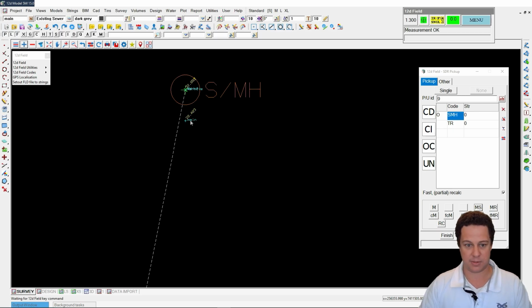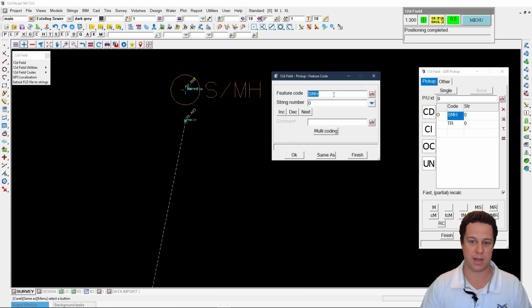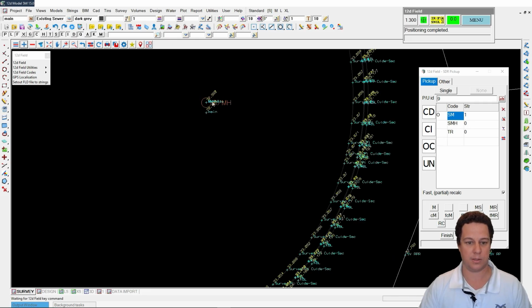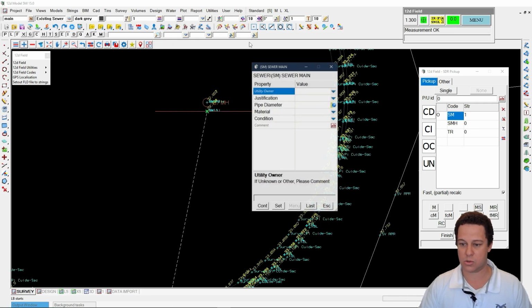Let's go ahead and pick up the sewer main. So I'm going to come to this guy here, and we need to change the code. So we'll come back to our CD button. Now I know that sewer main is SM, not SMH, so all I need to do is backspace that, give it a string number. Let's give it a string number of 1, and hit OK. I can now go measure store.